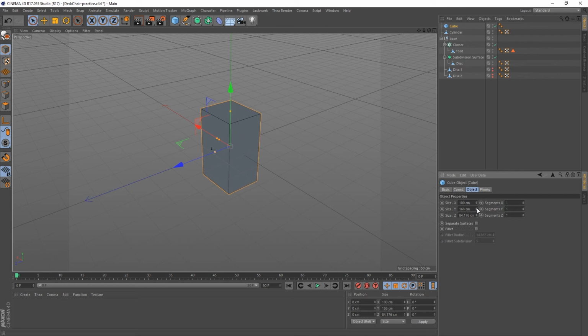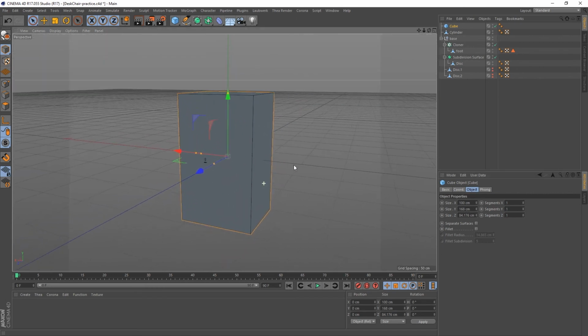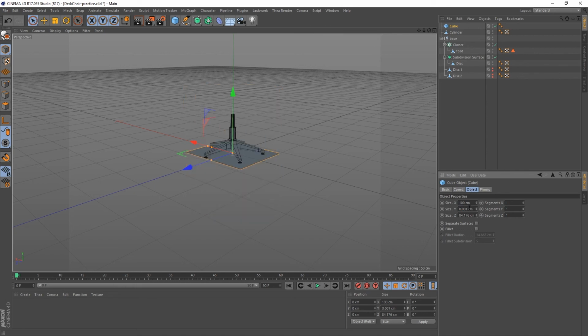Whereas in Blender, you would be able to just hold the Shift key and change the speed of the change to be more finite or brutto, whatever you want to call it. So that's how you do it in Cinema 4D. Again, Shift for 10s, Control for change in 1, and Alt for change in 0.1. If you need something very fine, you can type in 0.001 or whatever, obviously.